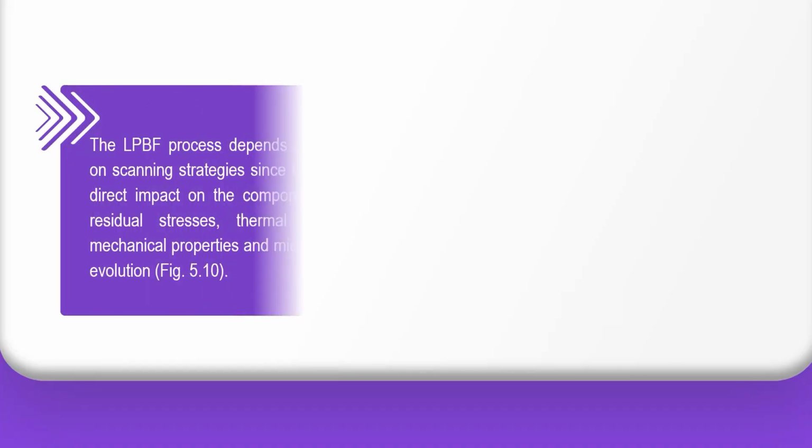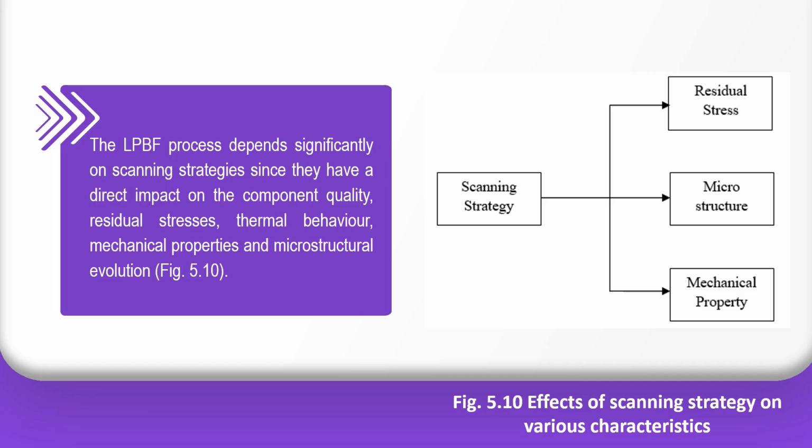The same analysis is also possible on the ANSYS platform. If you have an ANSYS based platform, similar data, residual stress, strains, and number of cycles can be obtained. So this is some effect of the input parameters, like the scanning strategy. It has been reported that it has a significant effect on the residual stress, the microstructure and the mechanical property. This is very important when we are interested to make some metastructure or exotic structure for typical 4D applications.